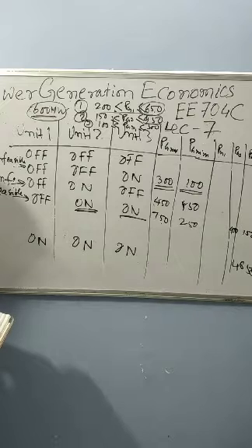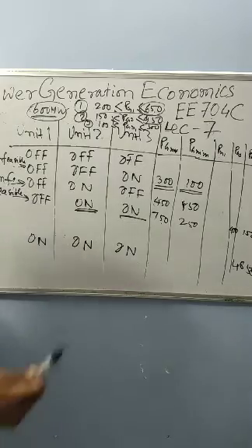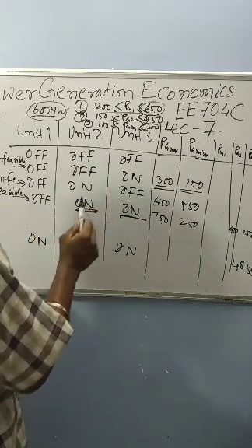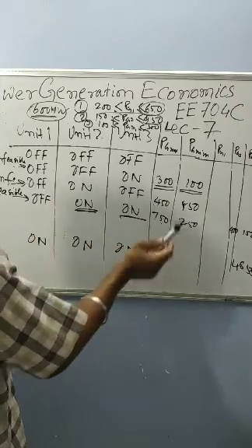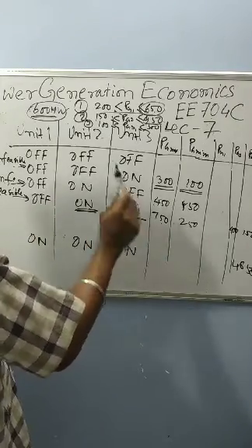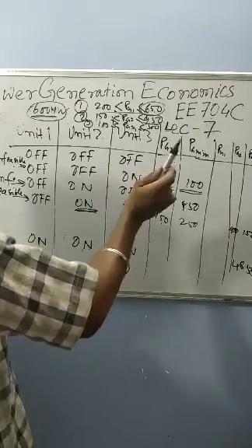The operating unit is closer to its best efficiency if unit 1 is operated, and the other units will be loaded further from their best efficiency points. Though the cost is minimum if I operate maybe 2 and 3 or 1 and 2, the efficiency operating point will be changing.